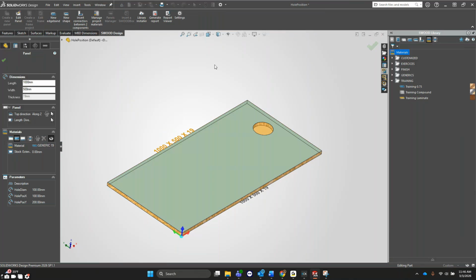The reason they make it easy to change the size in this is because you're going to be changing the panel size all the time when you bring that into a cabinet context. Because you might use the same material for your top and side, but obviously they're going to be different sizes. Does that kind of make sense? And in those frames, you're selecting planes, and that's how it's adjusting the size of the panel.